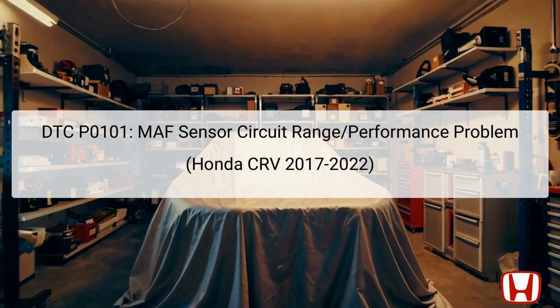DTC P0101 corresponds to a MAF Sensor Circuit Range performance problem, specifically affecting the mass airflow MAF sensor. This sensor plays a crucial role in measuring the amount of air entering the engine. The Engine Control Module, ECM, uses this information to adjust fuel injection and optimize the air-fuel mixture for efficient combustion.